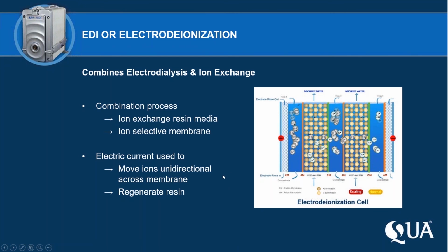And you'll hear a lot of different names for the diluting compartment: deionized water compartment, purifying compartment, and they're all analogous to each other. And the same on the reject compartment or the concentrating compartment, or as David referred to it, the waste stream. So the combination of ion exchange resin media and ion exchange membranes. And QAR's EDI stack does use ion selective membranes and a form of conductive filler or ion exchange media.